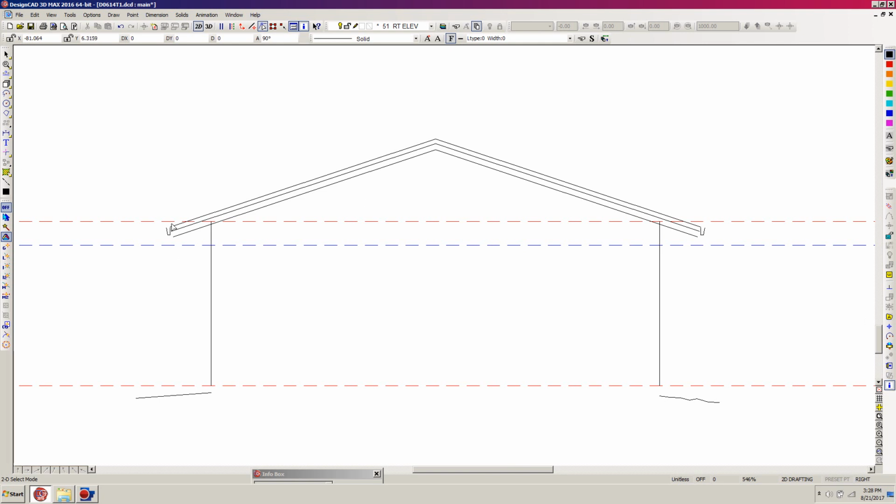One thing I'm going to do is I'm going to go ahead and draw a vertical, a plumb cut line down. So I'm hitting V for vector, zooming up right here, and hitting H for orthogonal mode, and coming down a little bit past this line here, and setting a point, and then hitting my scroll button to activate that command. And Shift E will trim these two lines to each other. I'm going to do the same thing on the other side. Actually, I could just use a parallel line, but I'm going to do it the other way.